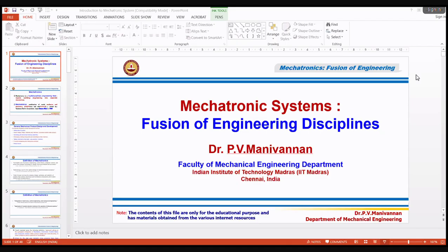In the ECU, you write programs which read this information. Based on the program, it may control fuel injection using pulse width modulation, correct, and control the throttle by controlling a motor, the throttle valve motor. So the engine responds to driver demand as per when you press the throttle. So the engine has now become electronically controlled.